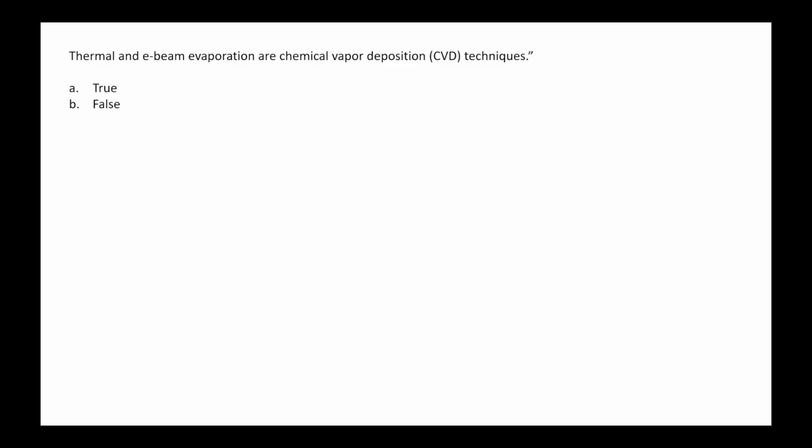Yes. So thermal and E-beam are both physical vapor deposition systems. It is an enclosed system, and they work in high vacuum. We require high vacuum in the chambers, and we use argon as an inert gas. In the E-beam, we use the electron beam, and argon also flows. In both cases, the inert gas flows during the deposition.